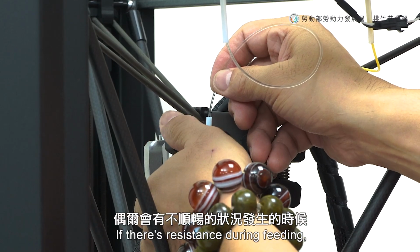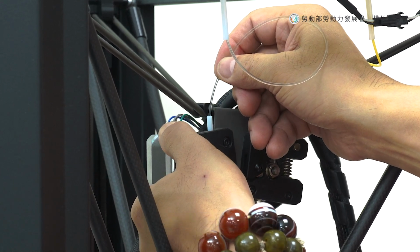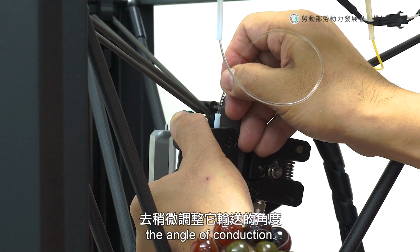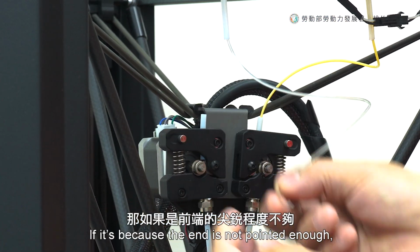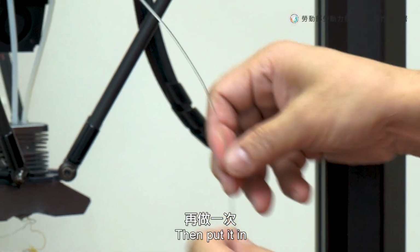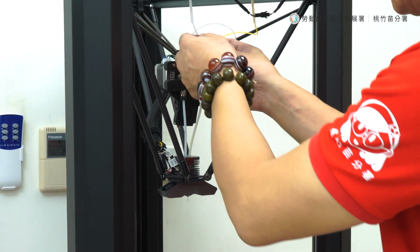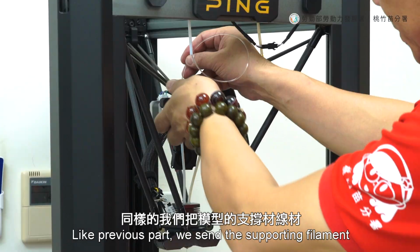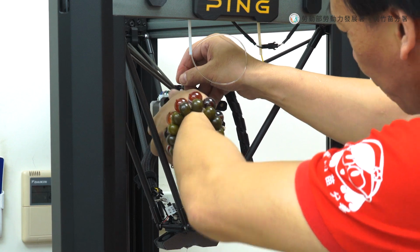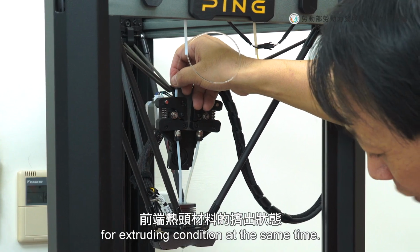If there is resistance during feeding, we can press this spring mechanism on the machine. The gear will slightly release to allow for adjusting the angle of conduction. If it's because the end is not pointed enough, we should trim it again. Then put it in the second tube again. Like the previous part, we send the supporting filament down the second tube. Check the nozzle for extruding condition at the same time.